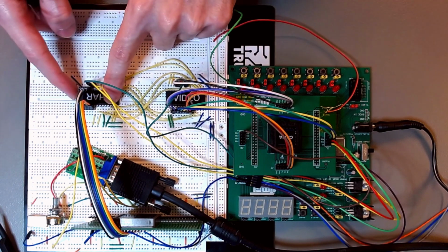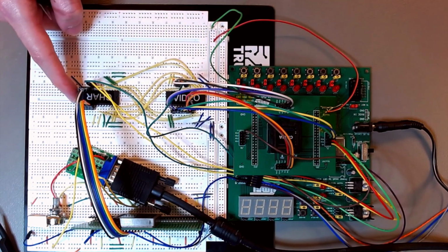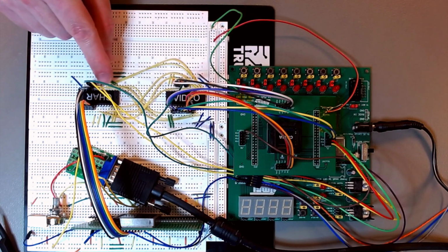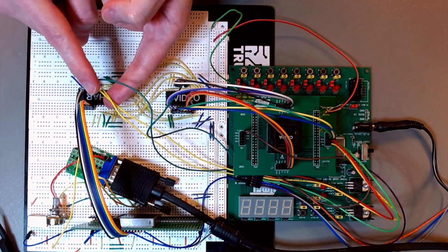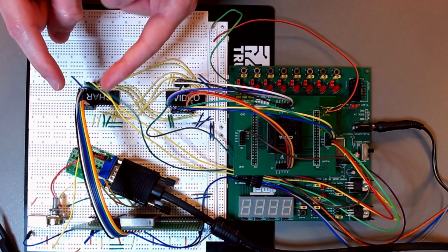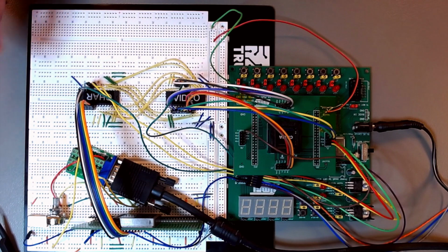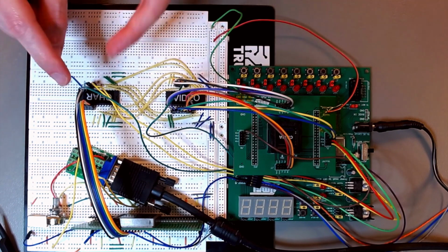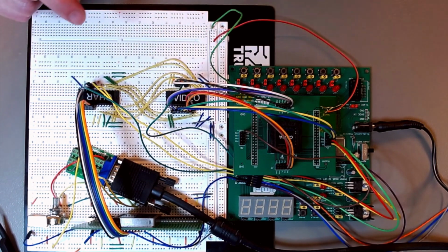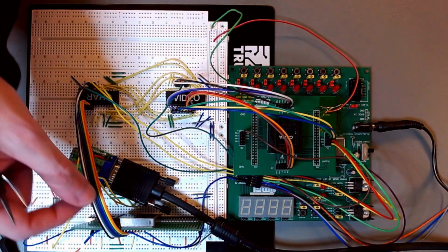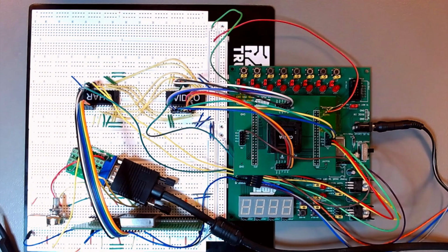The address for the character memory in here comes mostly from the video memory. It's the 8-bit output from the video memory, plus these 3 signals here, which are the most significant 3 bits of the line passes counter. We've talked about it in episode 2. And then the 8-bit output of the character memory goes in there into SCANC.